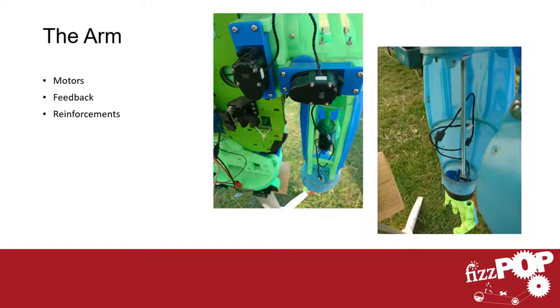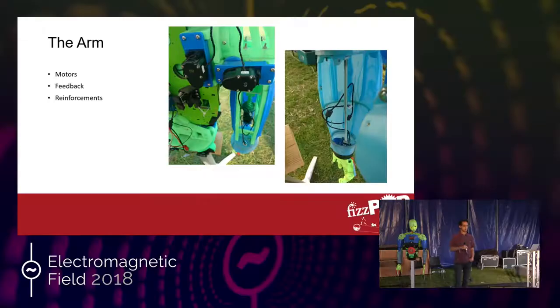I've ordered some parts, but I haven't got them yet, which is you can use separate encoders, and I would recommend using magnetic encoders because then they don't add any force on the joints, and they are more forgiving in the positioning. So you could fix a magnetic encoder on the joint straight, and you can get the feedback for the actual position of the joint.